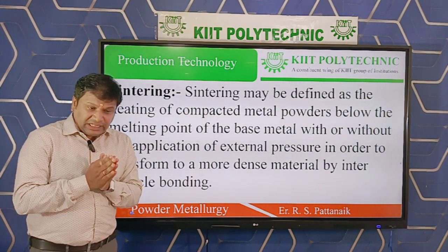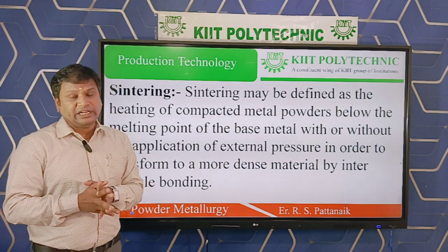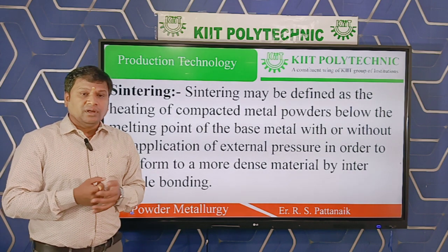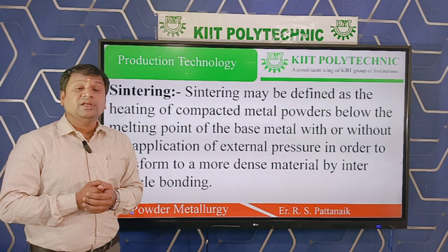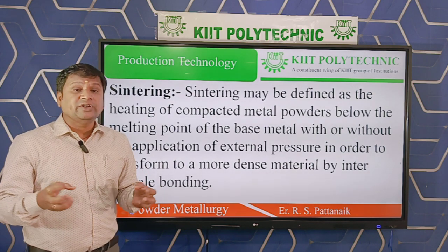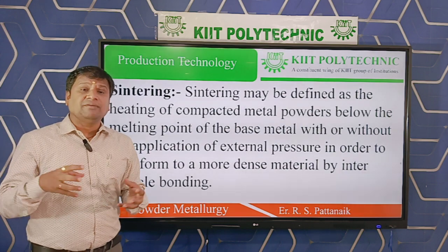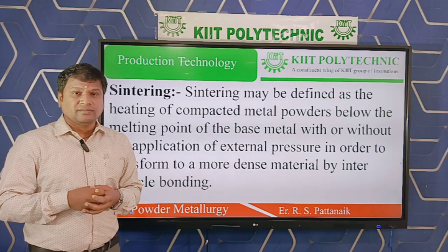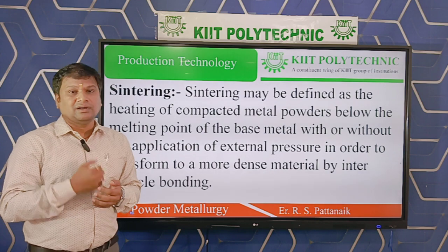Okay, so sintering, what is sintering? Sintering is the process of heating the compacted metal powder below the temperature of base metal in order to form the final component by interparticle bonding. Here the metal powders are bound together by interparticle bonding when heat is added.